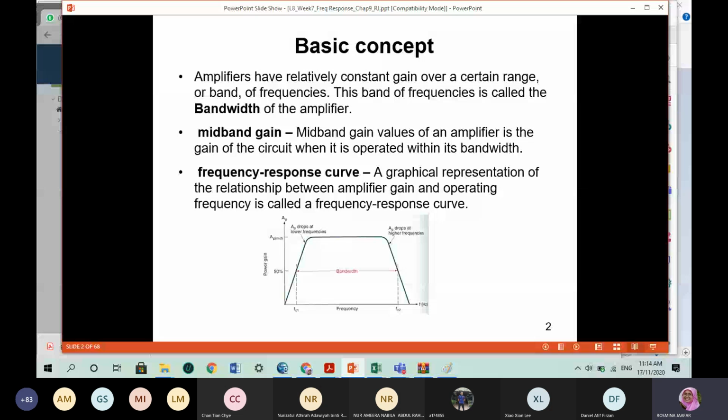So the frequency response curve always has a certain range, and the bandwidth is labeled as the lower cutoff frequency, FC1, and the upper cutoff frequency, FC2. The mid band is the range at which the frequency response is maintained. From this figure, you will see a drop at certain points. If your y-axis is in dB, it should drop at -3 dB. If the gain of the circuit is normalized from 0 to 1 or 0 to 100, the maximum will be the flat frequency response.